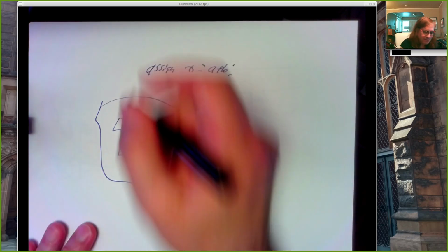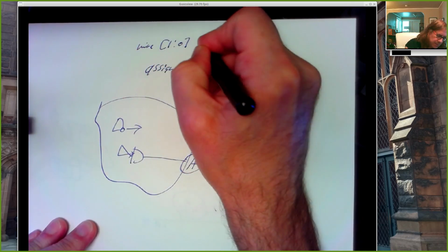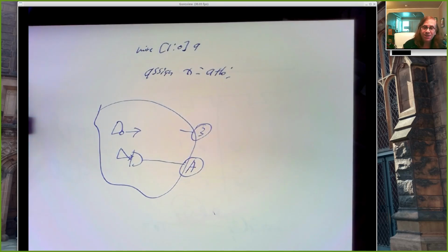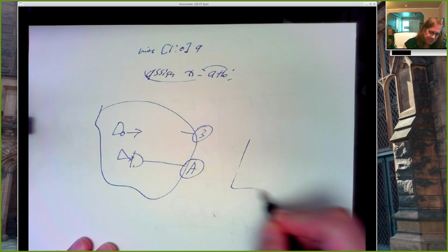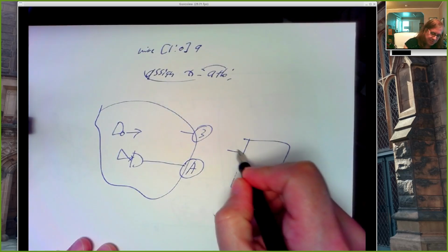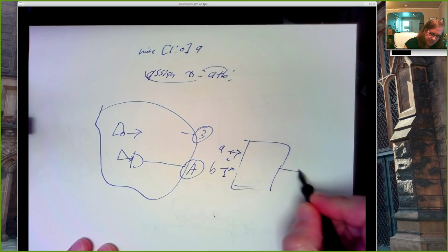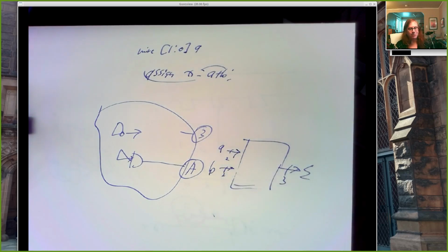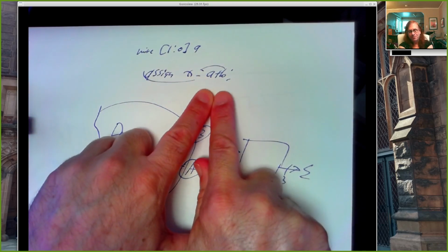If we declared wire [1:0] a and the same for b, it knew that we needed a 2-bit adder, and this would create some kind of block that we could feed two 2-bit numbers into and produce a 3-bit sum. It would build the logic with the XORs and the half adder, full adder, and all of that stuff, just by saying x equals a plus b.